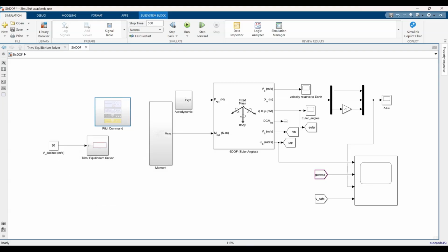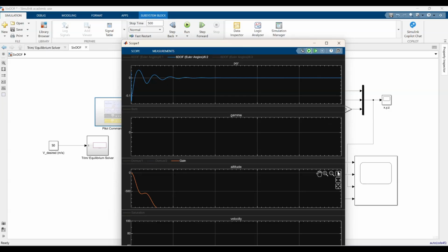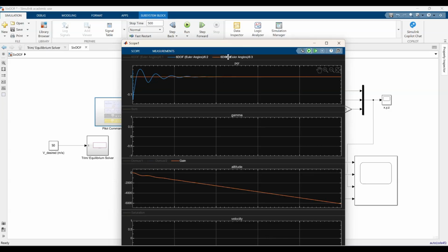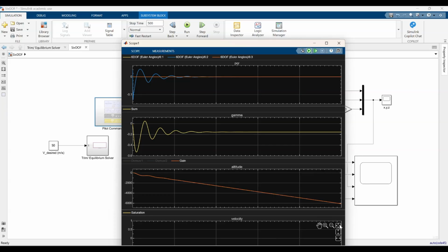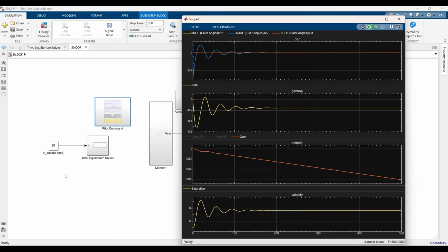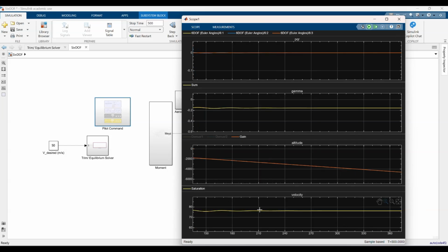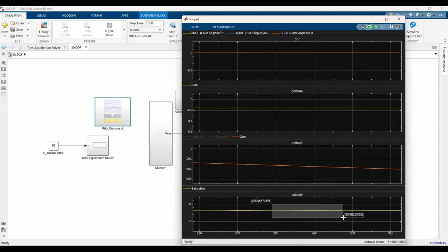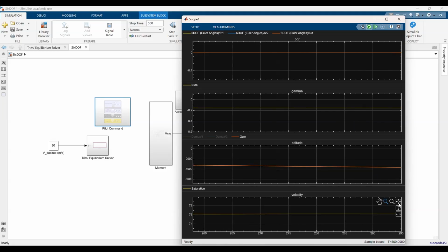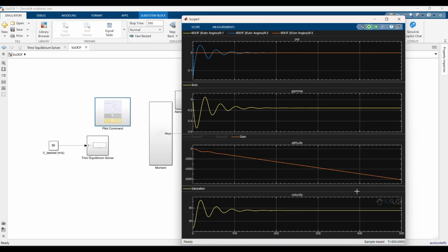Again, I'm not concerned about the altitude at this point because, like I explained in the beginning, no matter whatever altitude you are at, the equilibrium is equilibrium. The definition of equilibrium has to do more with velocity for now. And so, speaking of velocity, I want to check. Look, we gave a desired command velocity of 50, and it is able to hit that pretty close. It is able to hit the 50 mark pretty close. Is it? Looks like it is a little bit over, actually.